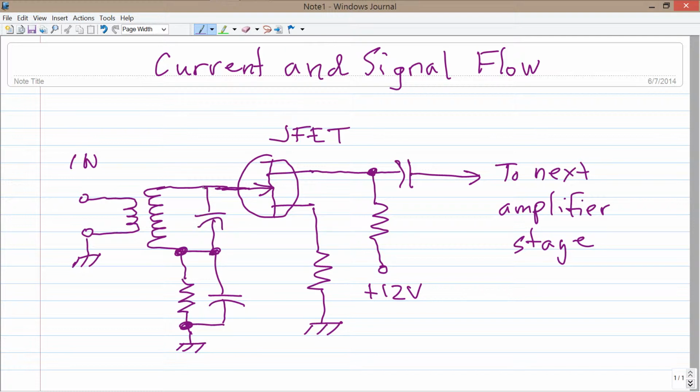Why am I adding that, you might ask? That will tune this particular circuit right here to pass signals that come in from, well, let's just say a radio antenna, like a short-wave radio antenna. Now we have a radio frequency preamplifier and preselector stage. The signals, let's deal first with the signal flow. That's somewhat different than the current flowing in the circuit.